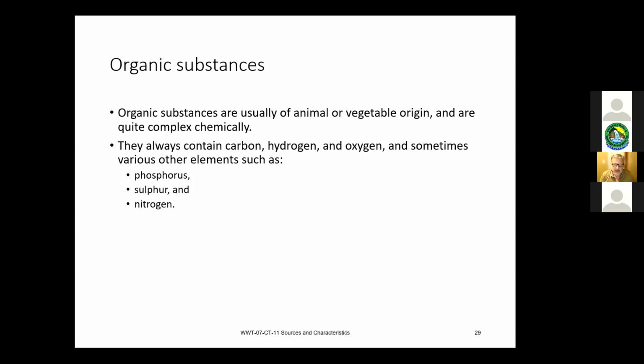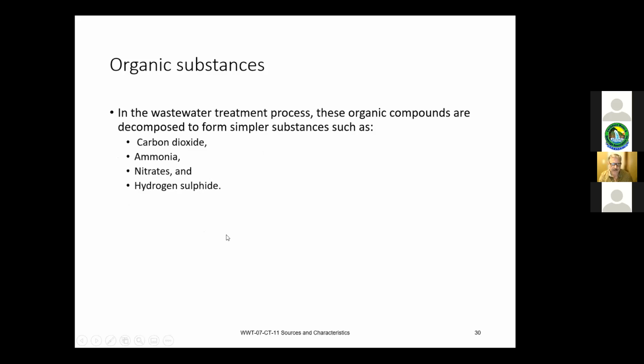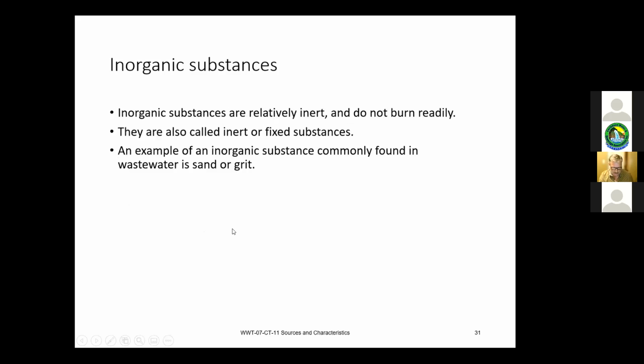The reason we need to do that is, if there's a piece of, I'll just use celery as an example, if celery hit your bioreactor, the microorganisms are not readily going to attack that piece of celery and break it down. They do, however, want suspended solids in a fine makeup that they can attach themselves to or swim around and grab and break down. Organisms will have nothing to do with large organic substance. There's basically nothing for them to live on.